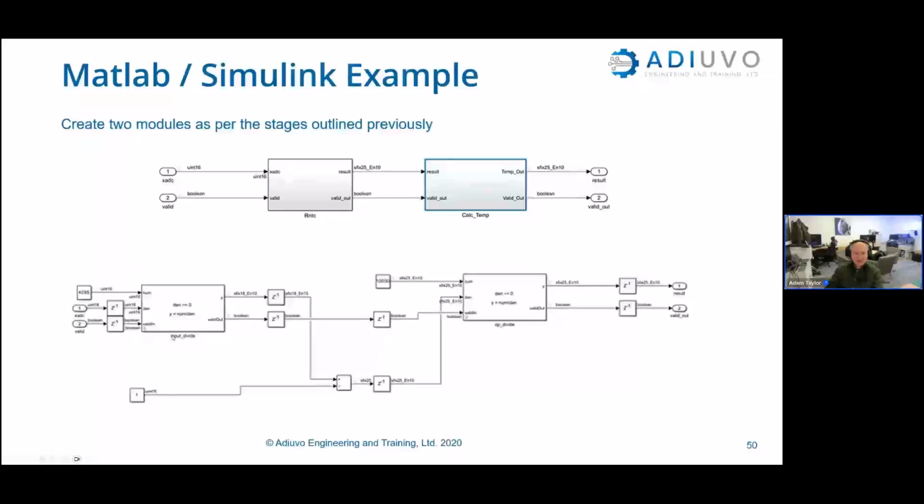So we're taking in a value here. It's a bit zoomed out. Actually, I'll show you the reality of it in a minute. But we're doing the division. The Zs are actually registers that are in there. We're doing a division, and then we're moving it through, and we're doing the input divide and the output divide against fixed values to actually get the final result that drops out of the FPGA. Now, all of this is in a fixed point number.